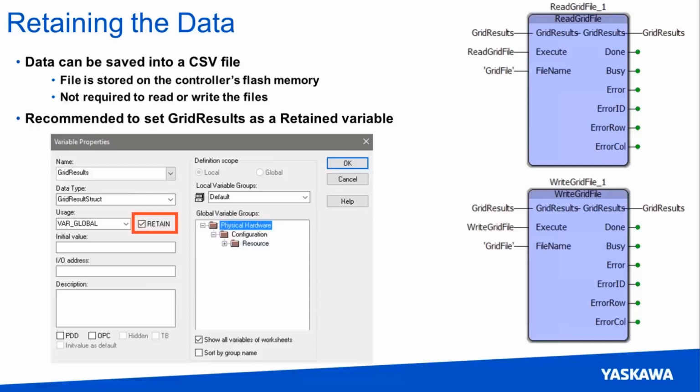Here's our cursor here. I haven't been moving it too much. So we have a question. Is the measurement done with respect to MCS or ACS? The measurement would be taken with respect to MCS positions, as the group is set up for a gantry in my examples. Torque measure method would require a gantry, but the analog or digital measurement methods could be done with any type of group or mechanism type that you have.